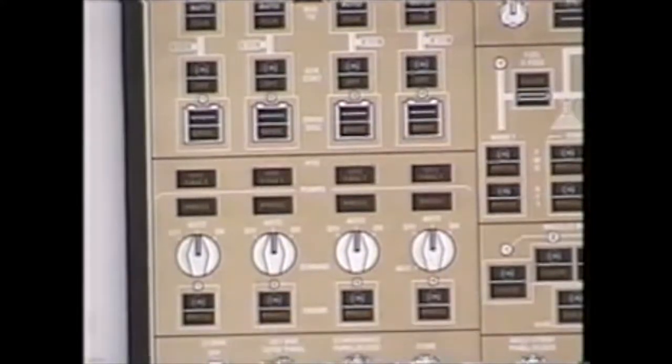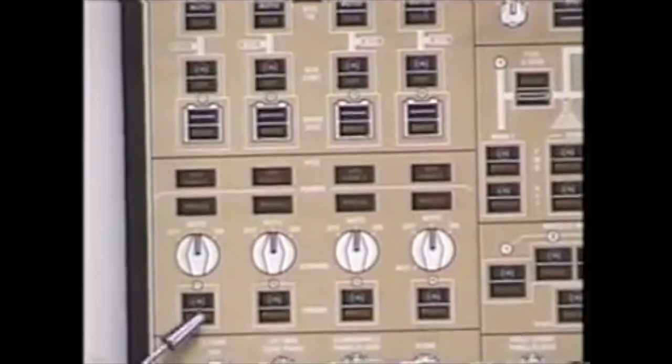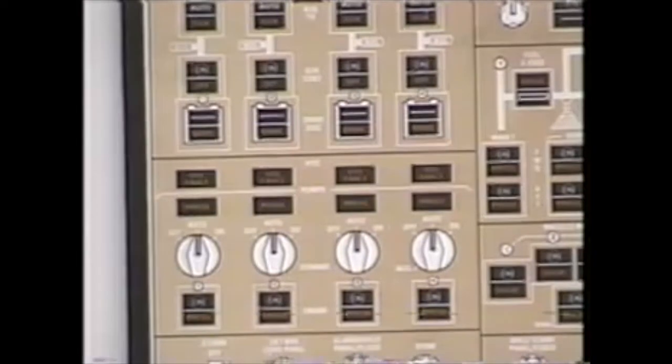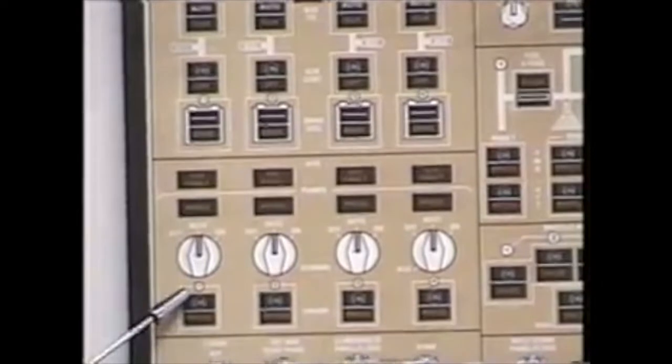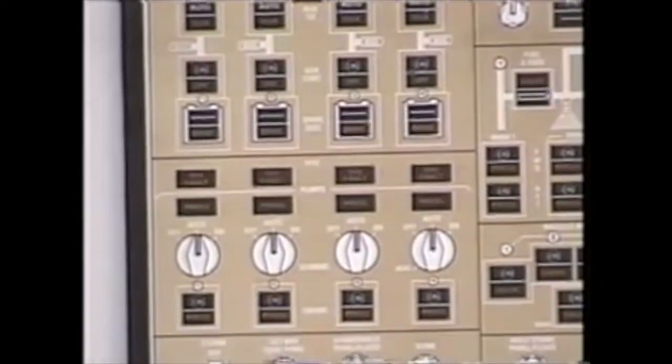EDPs for each engine is engine-driven pump. If the engine is turning, the pump will be turning, unless it seizes. For this discussion, we'll assume that the engine is turning. We're flying along at 30,000 feet doing .85 Mach. With the switch on and the pressure light out, the EDP is turning. It is putting out system pressure, and as a result, it is getting lubrication for cooling. If I was to reach up and turn the switch off, the on light would go out, the pressure light would illuminate. The EDP is still turning. It is not putting out system pressure, but it is getting lubrication for cooling.